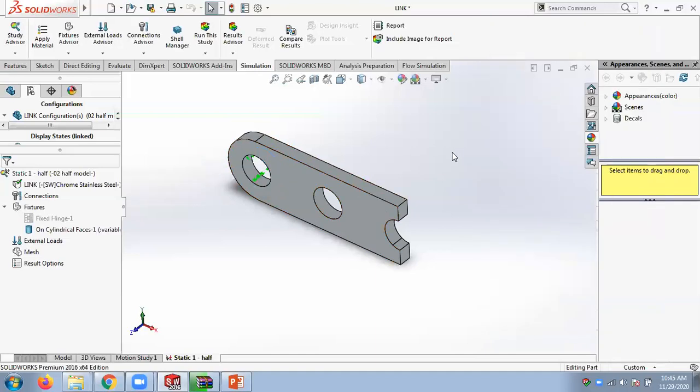So the hinge support is actually easy. Hinge support will take care of all these things. Or else you can give this kind of a cylindrical base. So either of these two will work. You don't need to have both conditions given. It's over-defining. I don't need to give over-defined conditions. Just give a fixed hinge support or a cylindrical. I hope you understood how it has been given. Any questions? Let me know.